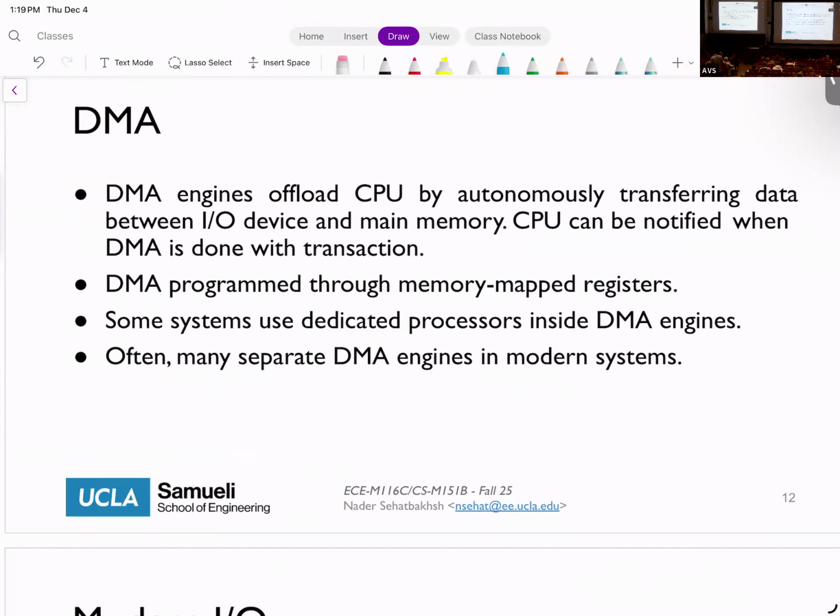And once the DMA is finished, it usually raises an interrupt, letting the processor know that, okay, I'm done with writing or reading, and then you can move forward. Of course, the security of this is also very important because you don't want to allow any IO to write anything arbitrary to the memory. So that's why usually the initiation has to be authenticated and done by the processor. But once you initiate that, you make sure that you can only write to those addresses and move on, okay?